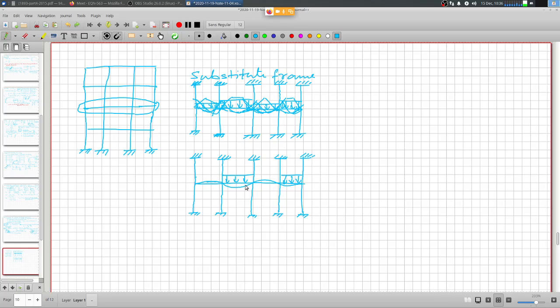So these are the two conditions, and dead load is of course there on all the spans, but imposed load is considered on alternate spans or two adjacent spans, and whichever is the critical combination, that is what is used to compute the design forces. So this is how.